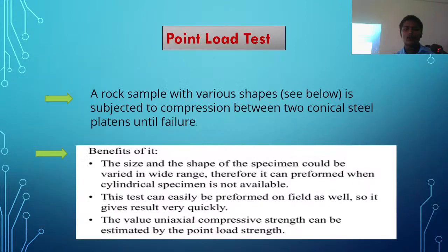Next, the point load test. It is a laboratory test. We use it to know how much load a rock sample can withstand when a point load is applied on it. What is the benefit of the point load test? With its help, we know how much compressive strength it can withstand, or the maximum load before it fails or fractures. So it will help us to choose the required rock or rocks in a construction.